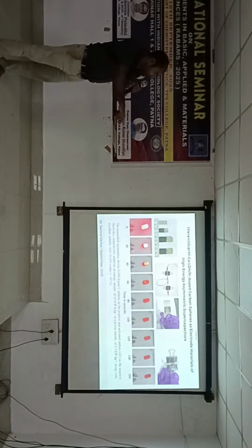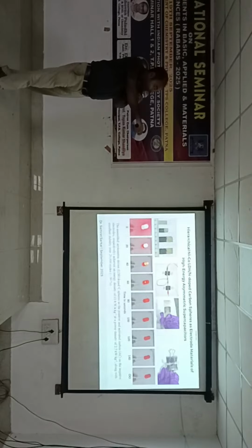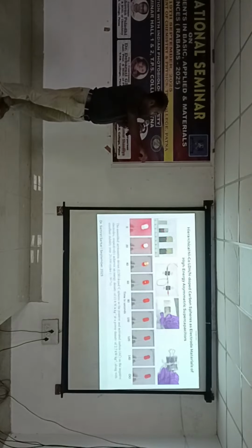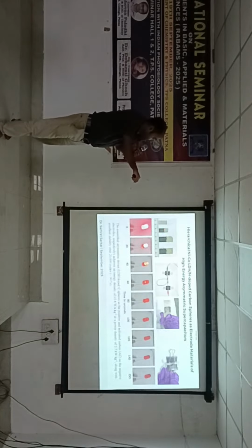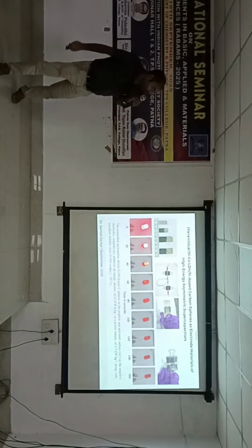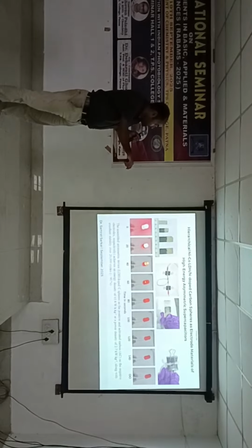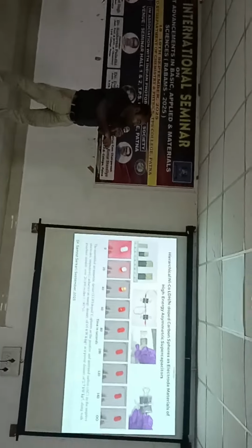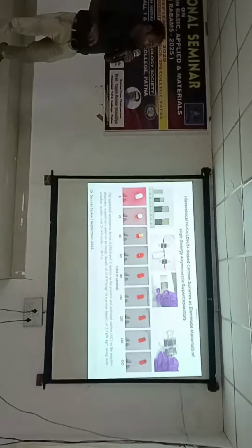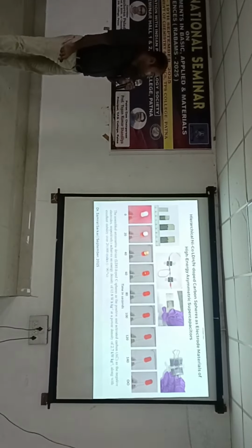So this is the assembly. The positive electrode is given, and these are the three electrode studies, separate electrodes. These are the device, and this is the demonstration by lighting up the lamp. And our device also shows very good energy density of nearly 65 watt-hour per kg and a power density of 2.7 kilowatt per kg.